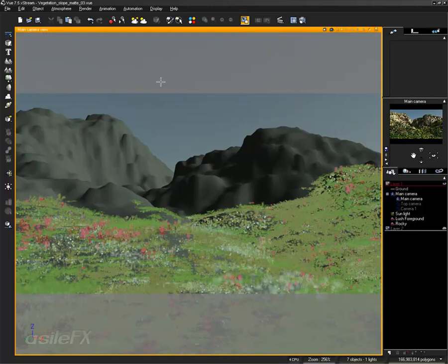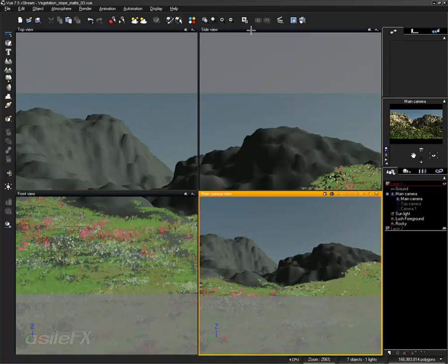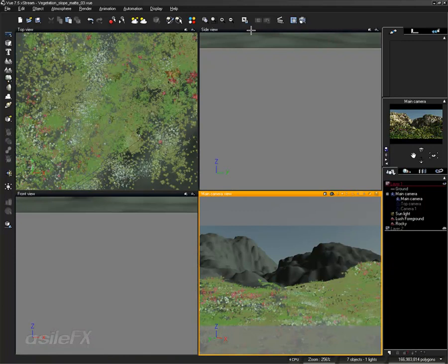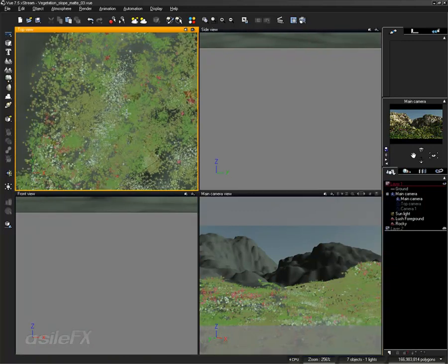What this bug is basically when you paint with the brush mode, instead of using the solid growth technology, which is growing new plants where everyone looks different, it ends up generating and creating several duplicates of the exact same plant. And that can really create some awful looking setups, and having plants really, really close together that are just the same plant duplicated over and over. So to avoid that, you can paint in the top view. This is also something that can happen in Xtreme if you're running this through another application. So it really is, I've only seen it show up within the perspective view.